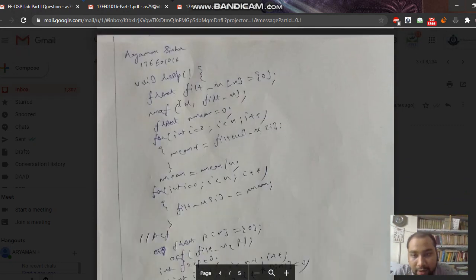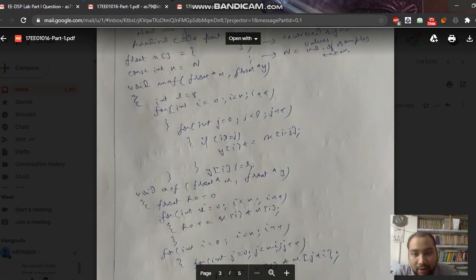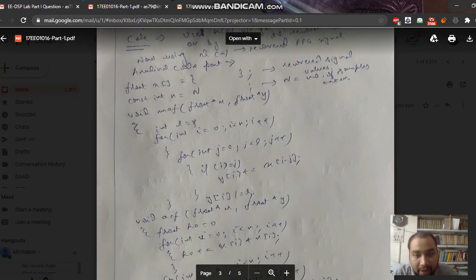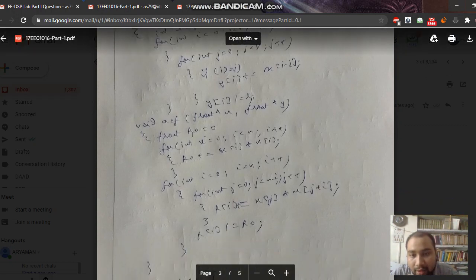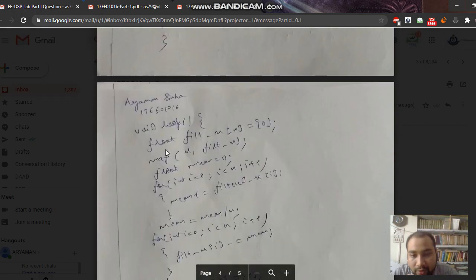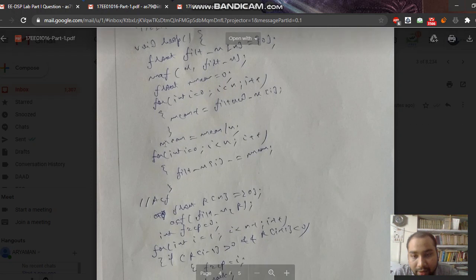First we will apply the MAF function, in which we have taken a window of 8, and use the basic moving average transfer function, which is shifting and adding the shifted original signal, and normalizing it with the window length.